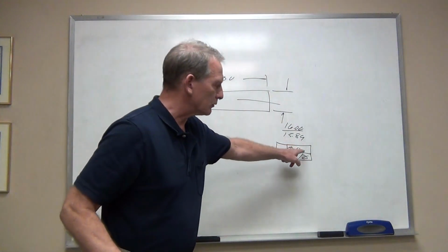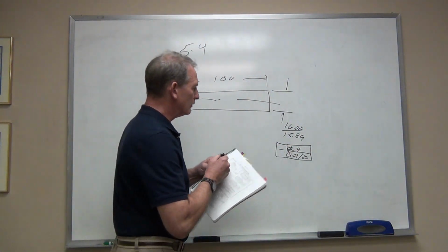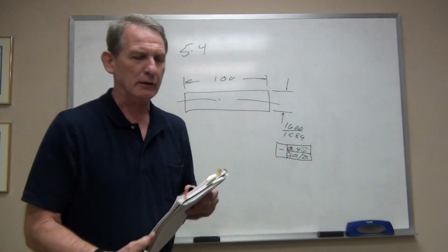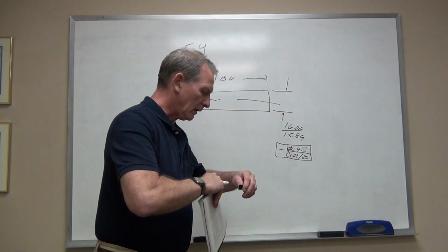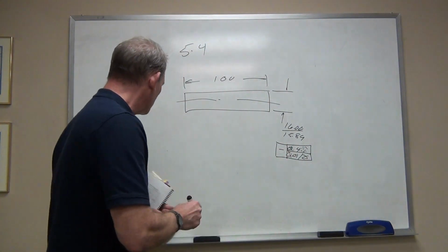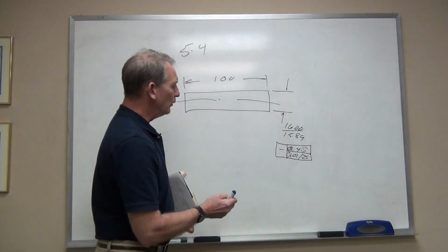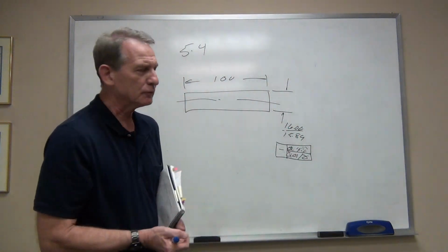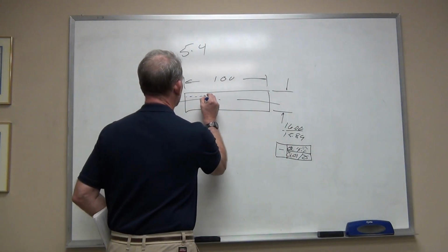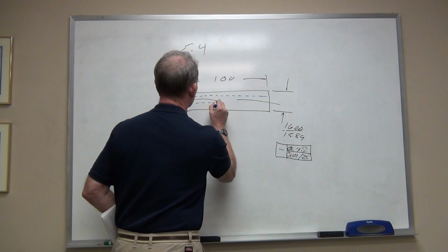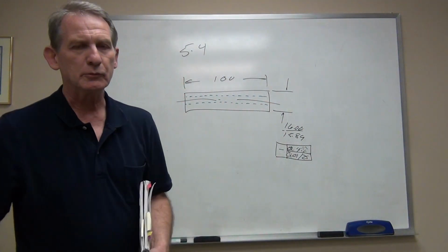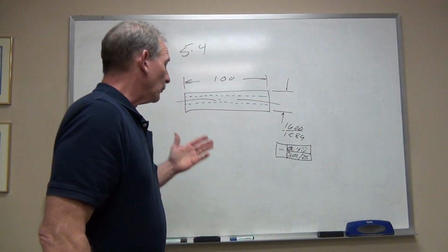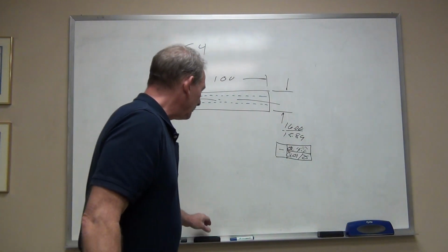regardless of feature size, since there is no material condition modifier here, you can imagine that an imaginary S is there. So that means that I have a diametral tolerance zone of 0.4. I know this is a derived median element because the feature control frame is attached to the dimension of size. The tolerance zone then is a cylinder that is 0.4, 400 thousandths, in diameter.